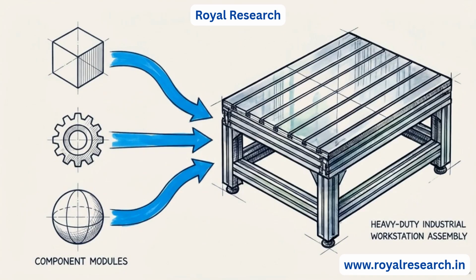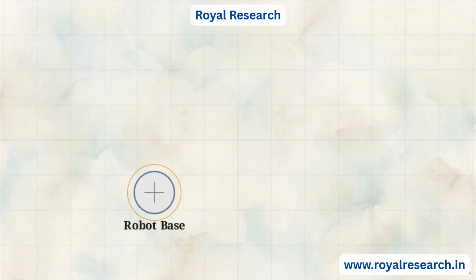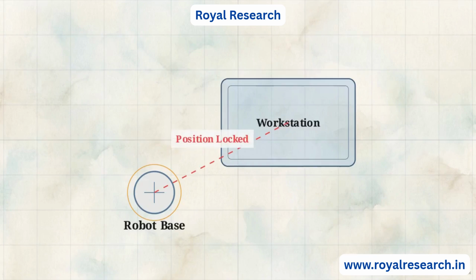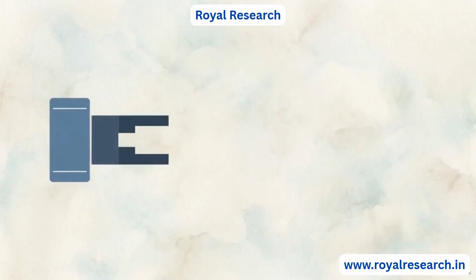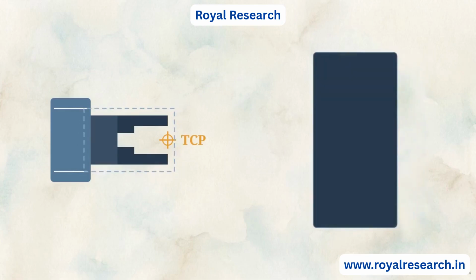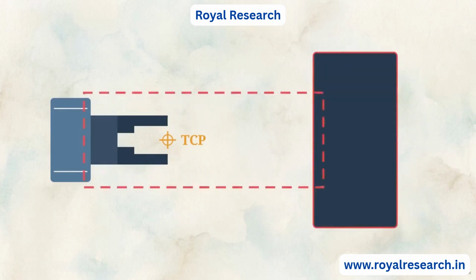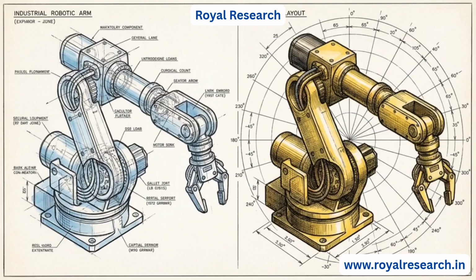Now we program the movement using targets. These are the specific coordinates in space the robot is required to reach. Position the robot arm manually in the 3D space and lock in the coordinate to create your first waypoint. Repeat this for every stage, creating a series of targets that define the robot's path. You can then organize these targets in the tree view, dragging them into a sequence to form a continuous, logical movement loop. Use the graphical programming tool to link these targets into a final executable script.